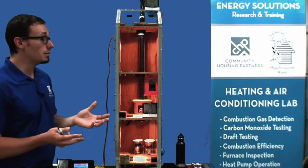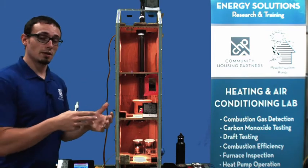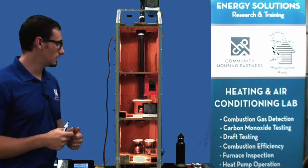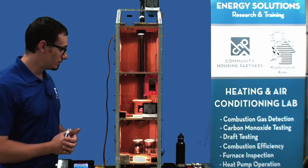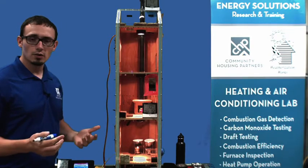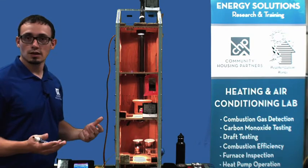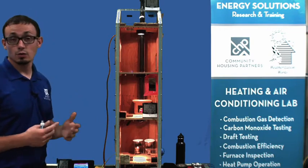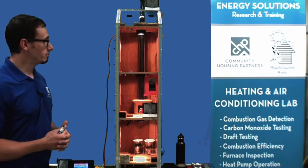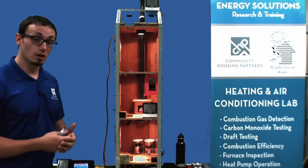If I've limited the amount of air that's going out of the building, I'm also limiting the amount of air that's coming back into the building. And the reverse is true if you were to only do the crawl space. But we know in most applications, we're going to seal both locations, seal all the penetrations, whether it's in the attic or the crawl space. We want to seal them all. But if we had to pick one to start, this kind of shows you where you want to start.